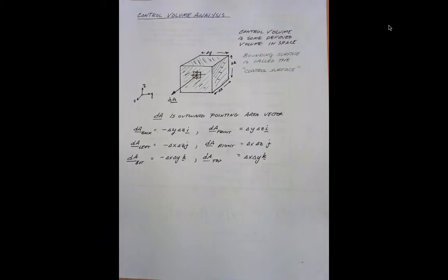And the conservation of energy in a system simply says that the rate of heat flow into a system minus the rate of work done by a system on its surroundings is equal to the rate of change of energy in the system. And the last one is entropy. It says the time rate of change of entropy for the system is greater than or equal to 1 over the temperature multiplied by the rate of heat flow into the system.